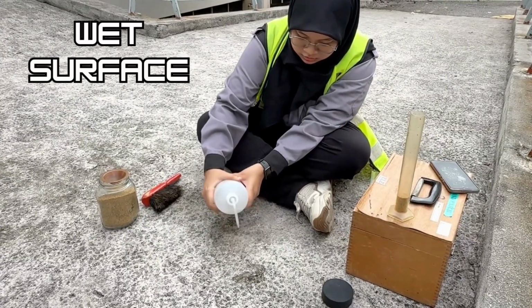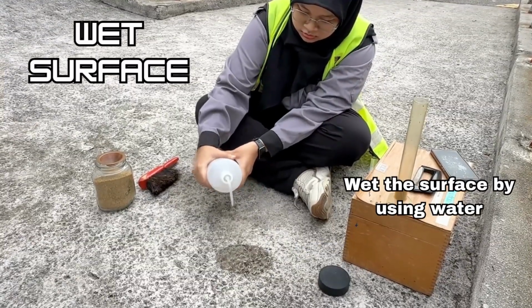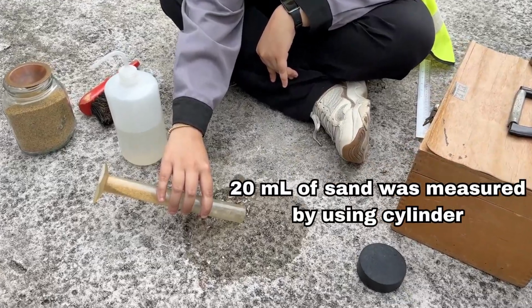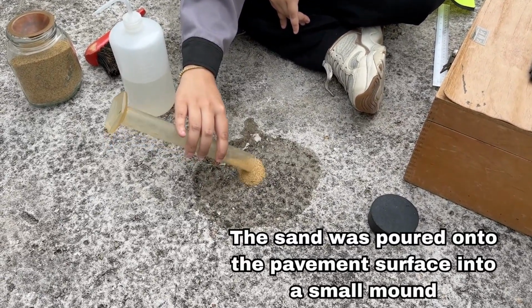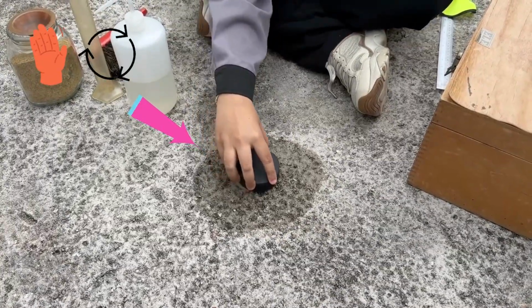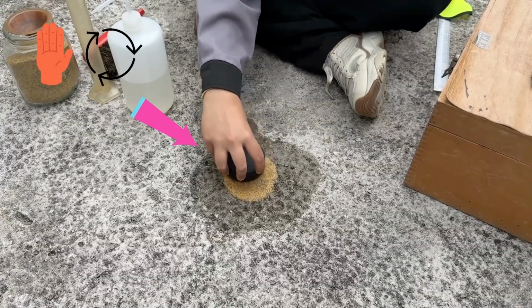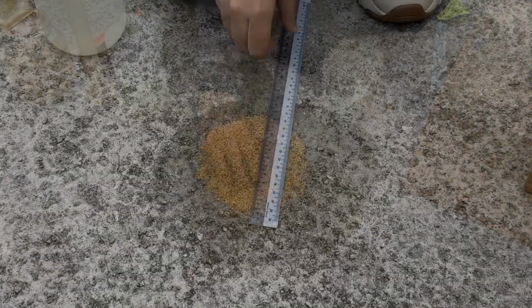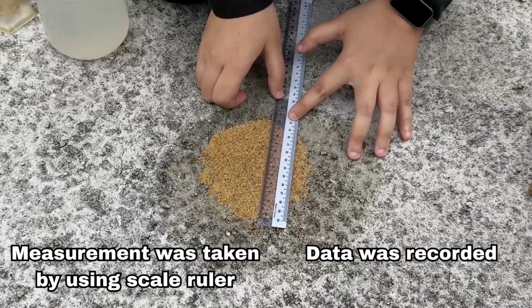Now, we conduct the experiment for wet surface. Firstly, wet the surface by using water. 20 ml of sand was measured by using cylinder. Then, the sand was poured onto the pavement surface into a small mound. Next, the sand was evenly spread in a circular motion using a circular block with light pressure. Measurement was taken by using scale ruler, and result was recorded.